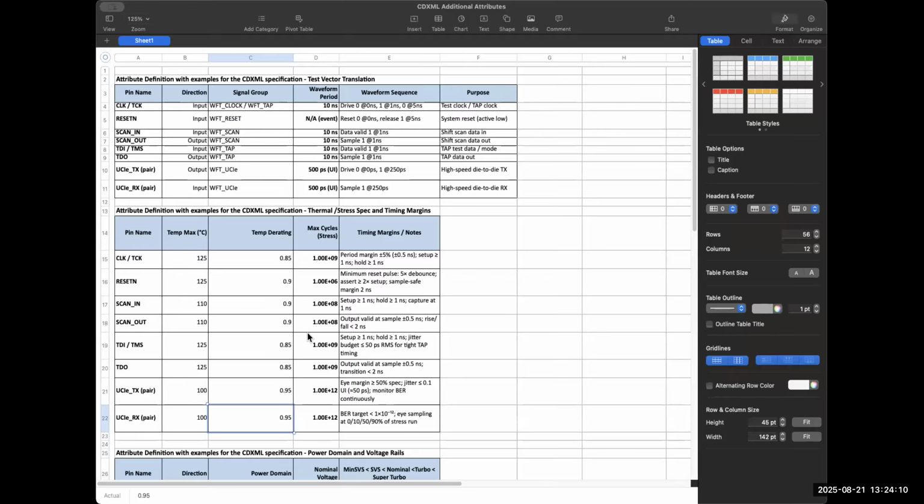But if it's going through an OSAT, then the chiplet company would provide the patterns to the OSAT for wafer sort. It's possible, though not likely, that the system integrator buying the chiplet may also choose to rerun wafer sort. That's probably not a standard model, because the expectation, if you're buying a chiplet, is that it's already pre-sorted.